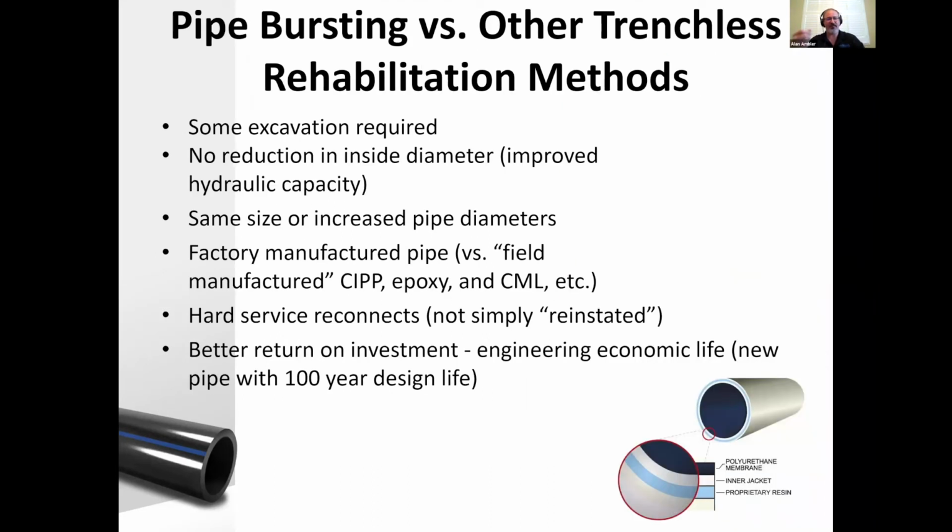Yeah. And another one is the reduction in damage of existing utilities. We'll talk a little bit about some of the design around pipe bursting and pipe bursting around other utilities, but most open cut excavations, damage to utilities is done by the tooth of digging ditches. So we're looking at pipe bursting versus other trenchless methods.